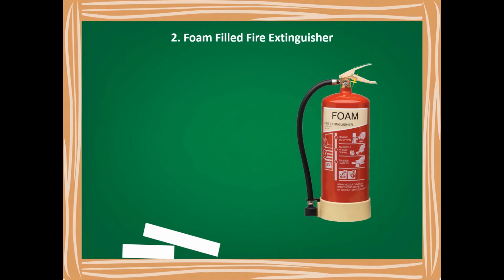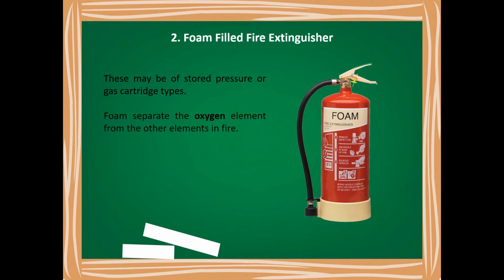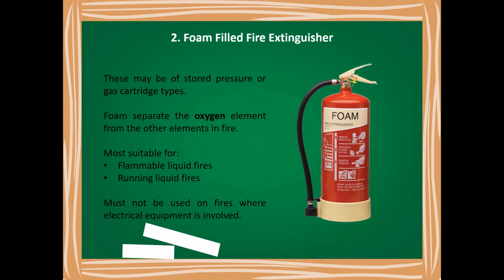Foam-filled fire extinguisher. These may be of stored pressure or gas cartridge types. Foam separates the oxygen element from the other elements in fire. Most suitable for flammable liquid fires, running liquid fires. Must not be used on fires where electrical equipment is involved.